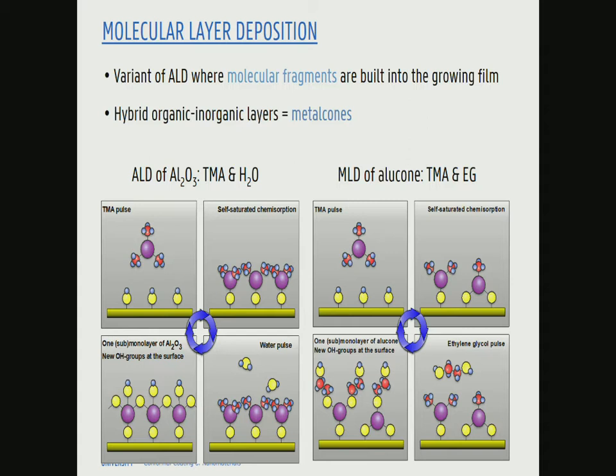Very briefly, only one slide. HYCOAT is not really about atomic layer deposition, it's about molecular layer deposition. So what is molecular layer deposition? It must be something different. In essence, it's very similar. That's also why I put both schemes here next to each other. It's very similar to ALD. So it's also a cyclical exposure to precursor vapors and in this way building a film.